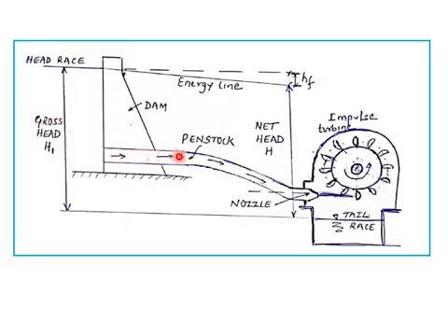When the water flows, there is always resistance to the flow. So there is always some loss. That means some energy is consumed, and hence loss of head takes place. This loss of head is mainly due to the head loss due to friction. That's the reason why whatever head is available to the turbine is known as the net head.